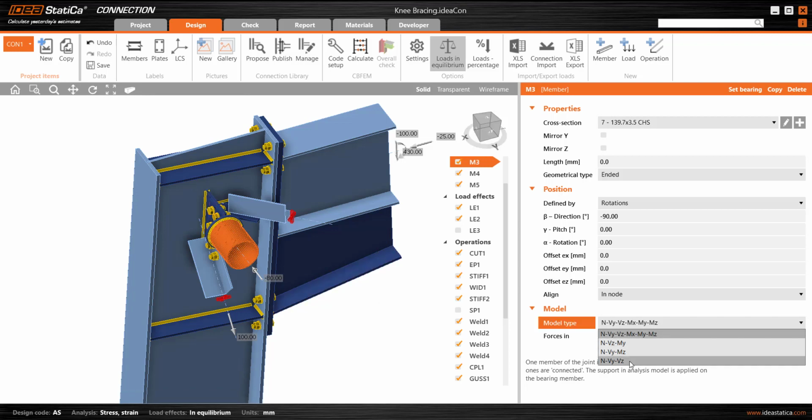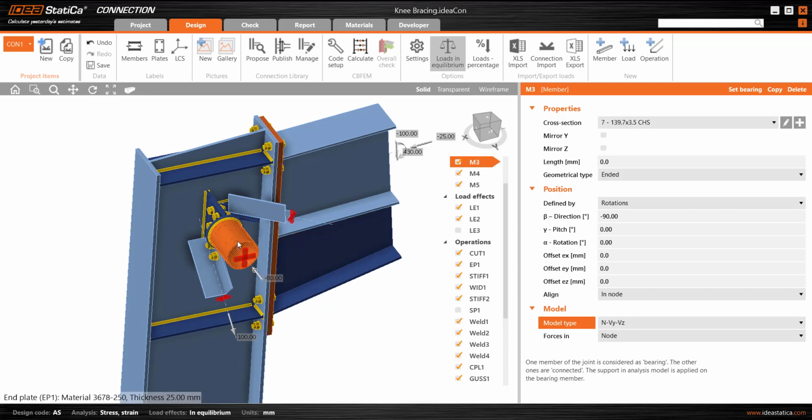But the other model type, the model type I will use, has a moment restraint in the buckling analysis, but no sway restraint. So there are some implications in terms of the buckling review and the minimum buckling load factor that you need, depending on the model type that you use. And I recommend some articles in the StatiCa Support Center. Simply search for buckling and you can review a number of articles about these aspects.